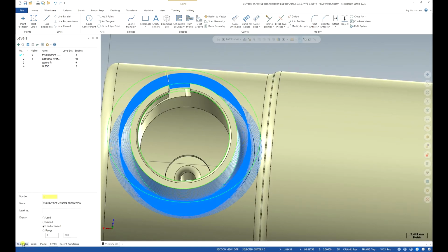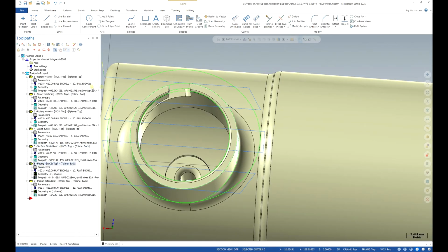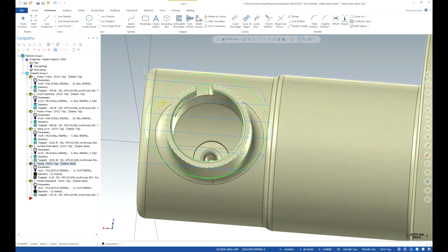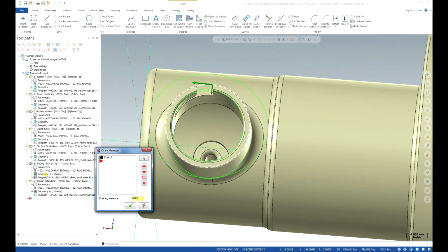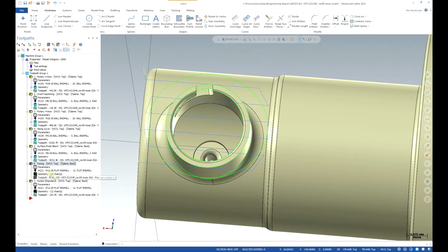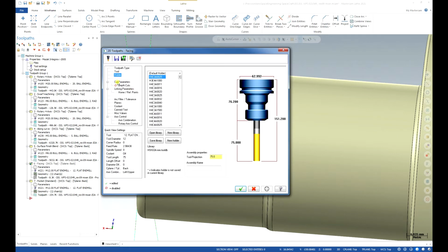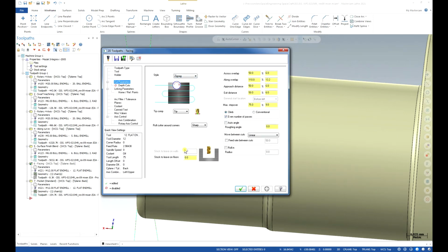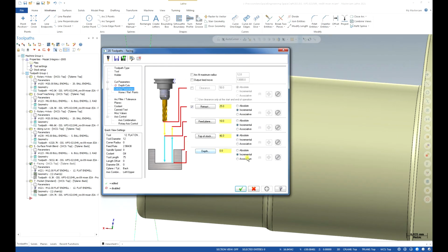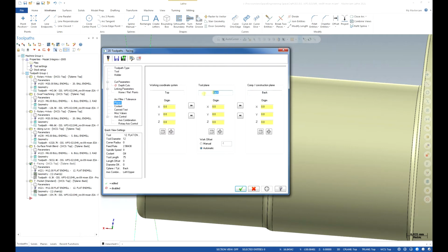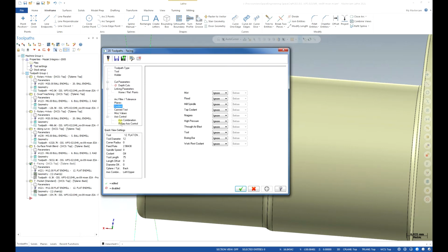First of the toolpaths is facing that I programmed. So this is the toolpath. This is the chain I selected for this. And the tool I used is 12mm, this holder, and zigzag method, incremental depth 0, and on the plane tab remember to keep the tool plane and construction plane set to back.